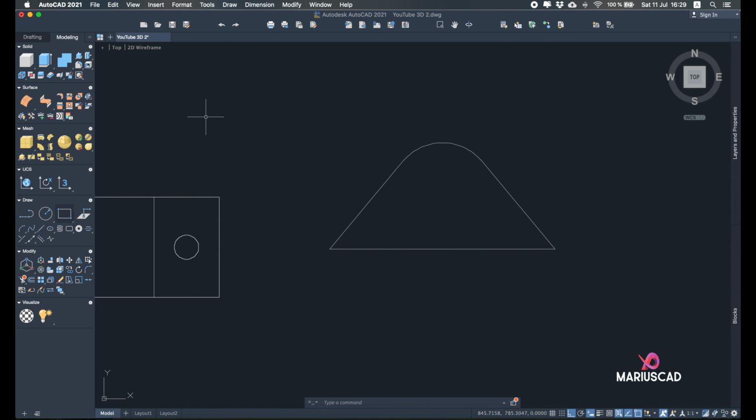Now let's build the other 2 circles again. So go in this arch, find the middle. Yes, exactly this. Go with 12.5 units now as the radius, and another circle from the same center, 25 units again.